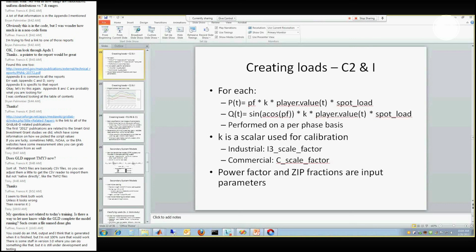Yeah. And obviously this type of simulation isn't going to show it directly, but we're trying to do stuff at 1 minute levels, and if we can see some kind of significant difference, you know, we're trying to yank our solar full on, full off at noon, things like that, and see what type of variations. Most grids are robust enough that they're not going to show severe problems there, assuming you've got the nominal voltage coming into the substation, but we would like to imply where there might have been flicker in cases like that.